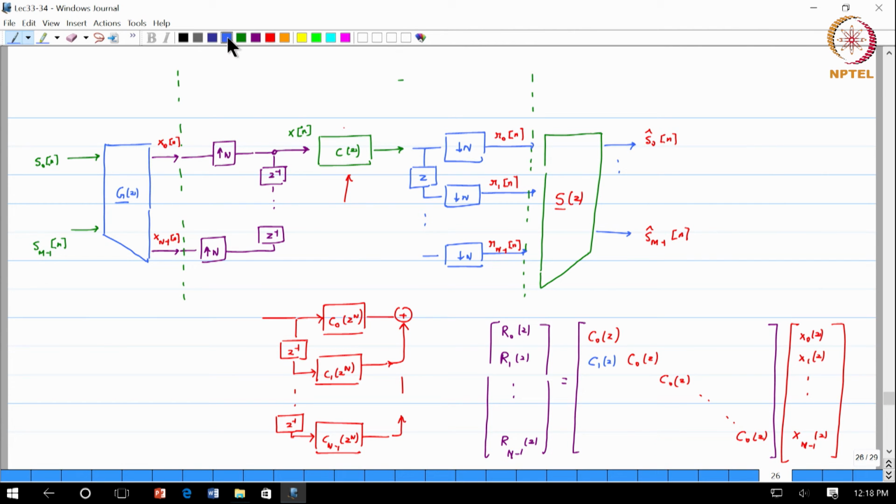All the one lower diagonal, all of them are C1s, okay, and all the way up down here C1 of z. Then comes C2 of z. Now, any matrix that has got this is called a Toeplitz matrix. Okay. Now, very interesting. What is the transfer function between R naught and x1 will basically be the second element here, right. So, if you go ahead and fill out all of these entries, this last one will be Cn minus 1 of z.